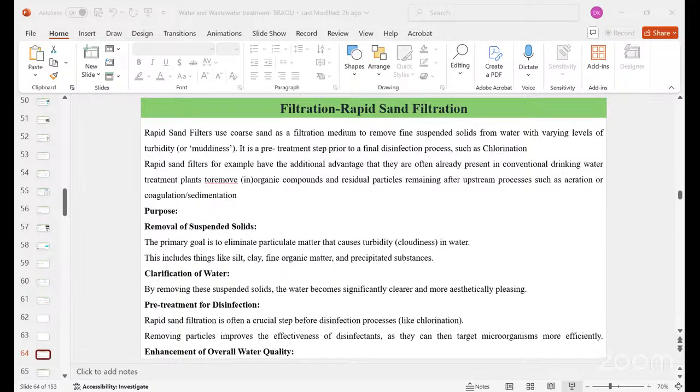The typical range for different kinds of media beds, in terms of pore size, granularity and so on, majorly ranges from 4 to 15 meters per hour. It can vary based on the specific application and source water quality, and the filter media characteristics as well.